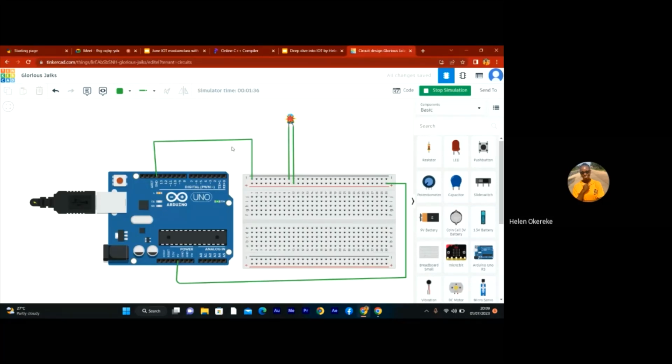So if we are looking to communicate with our phone using this Arduino board, then whatever you are connecting, either the Bluetooth or the Wi-Fi, we connect it to pin 0 and pin 1. These are the transmission and receiving pins, so we will not use pin 0 and 1. We just kept them aside for that. The pins we have left are digital pin 2 up to digital pin 13.